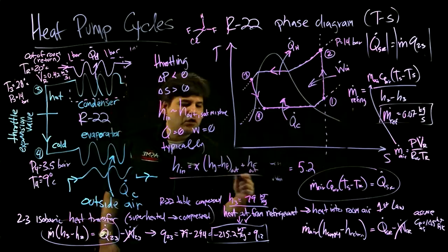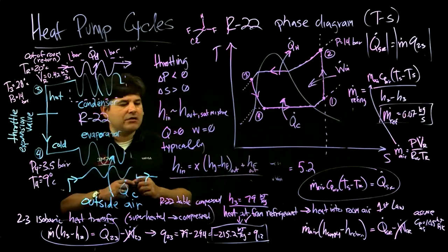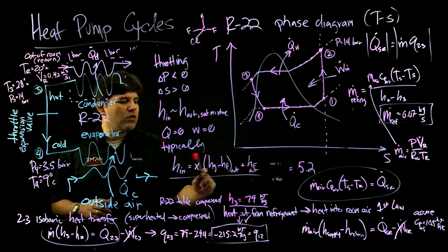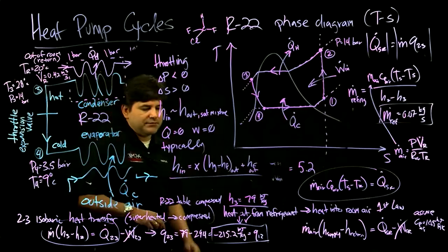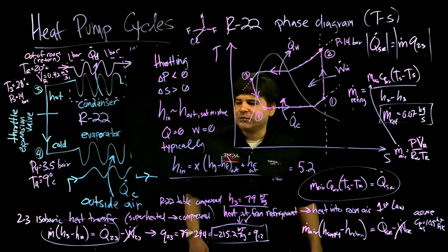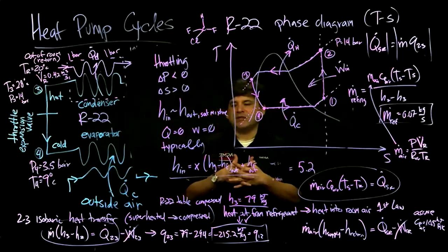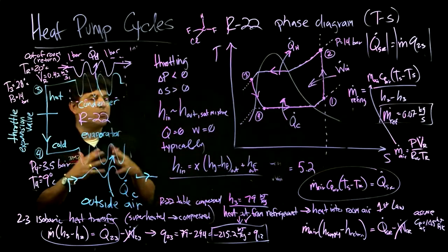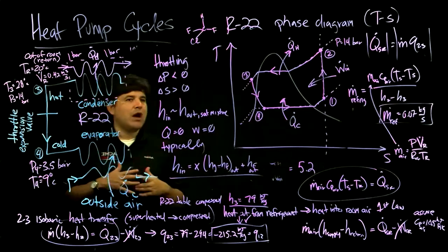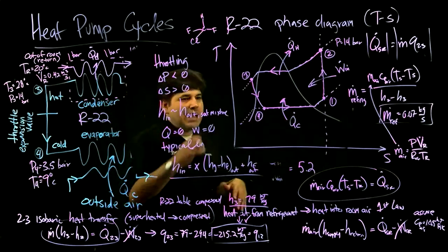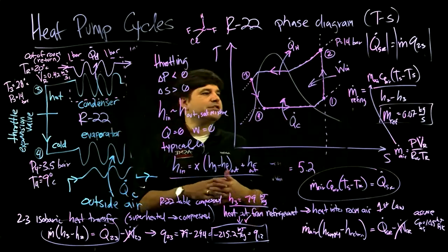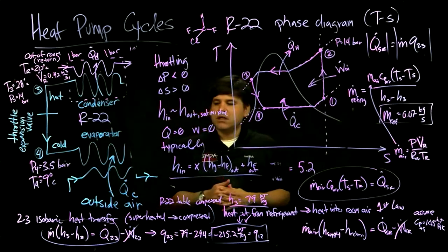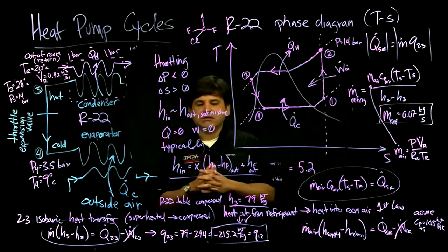So there's typically a quality at the outlet, and you balance that out according to whatever the steam table will give you, that row with the enthalpy you had coming in. So those are some unique things about these heat pump cycles. There's a lot of similarities with refrigeration cycles. They're both reverse heat engines. They both operate around these refrigerants, and they both have these throttling conditions here, and they have these mechanical work requirements as well. All right, so thanks, and I'll see you guys next time.